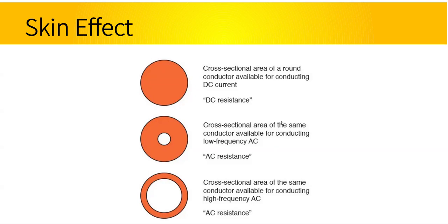Used to see it in old tube type transmitters, and they use not tape, but copper strip off of the plate voltage to carry the current because of skin effect. Antennas at high frequencies tend to be tubular instead of solid because nothing in the middle matters. Back to what you were saying about the tubes, I've seen in commercial transmitters copper straps that are almost a foot wide. Yeah.